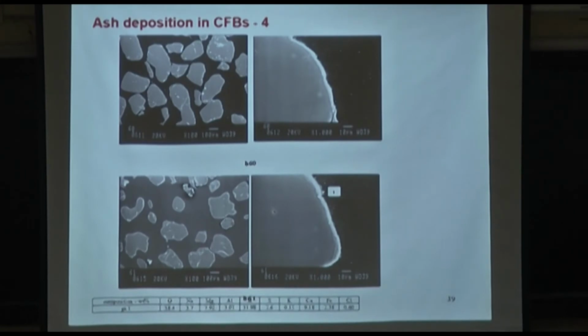One is by bringing in additives, aluminosilicate clays, which will dilute it so that it will not remain sticky anymore. That's one option. Or preferentially, if we have them, the clay materials, if we use them in such a fine particle size, much smaller particle size compared to the bed materials themselves.